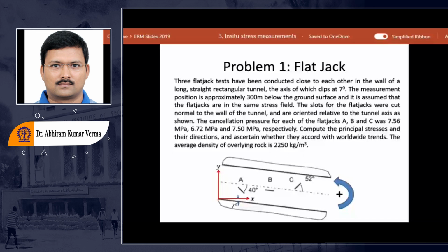So this is also happening when we are making an underground opening or surface opening into the rock mass. These stress fields are getting affected, and the stress fields are getting shrunk and concentrated at particular points, and it will follow a point, and then again it will rejoin. So that's why the concept of in situ stress and induced stress is coming.